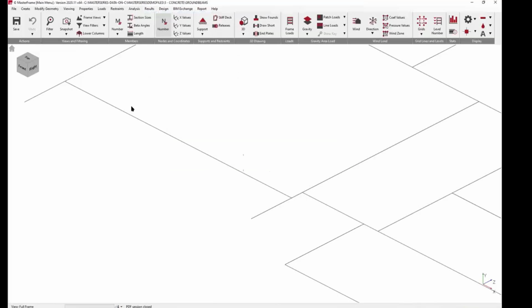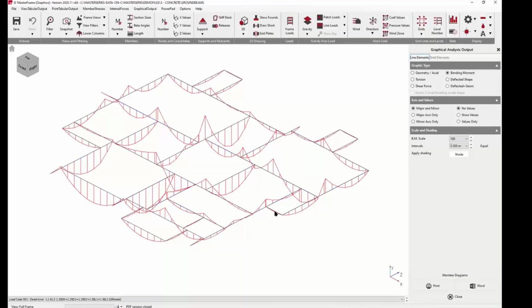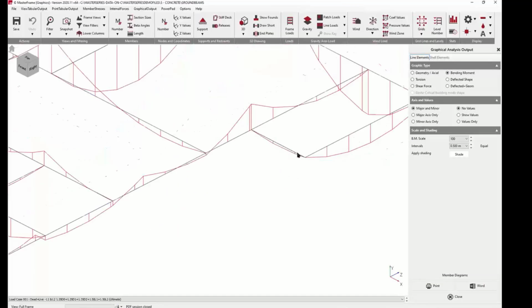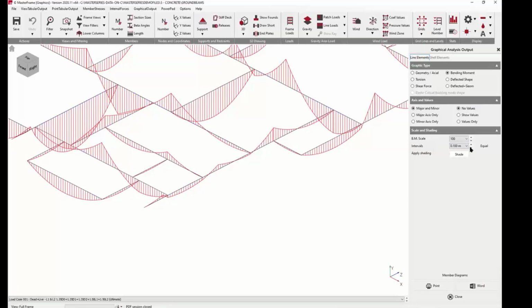So analyze, static analysis, very, very quickly. Grillage again, results just for one second. And we will see our bending moments without our fixed end moments, just pinned as you would have done by hand. Continuous throughout the length and then pinned. Obviously this cantilever here is causing a little kick around. But if you look at one of these, and I'm just going to pull the hatching down because the more hatches we have, the smoother it is.